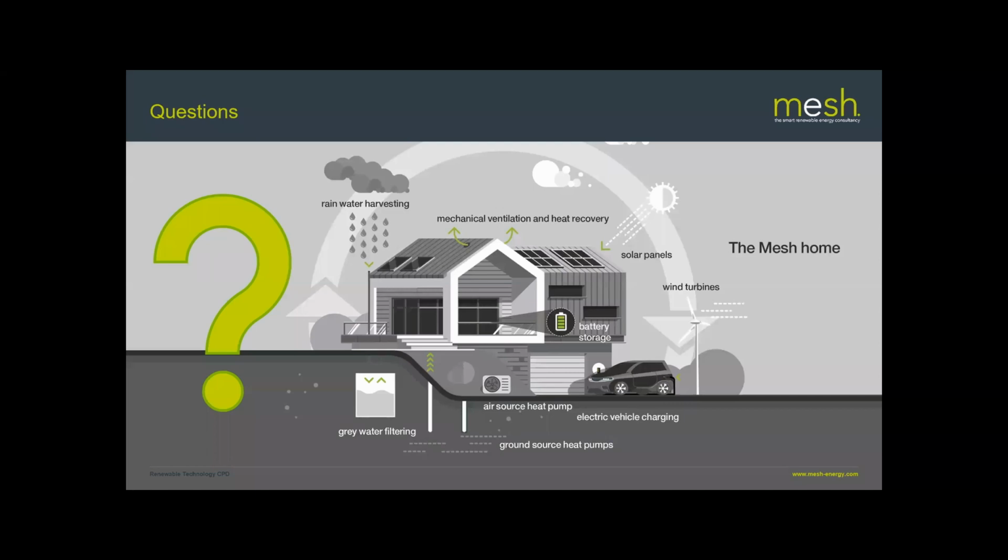So what we do is, as a standard, when we're doing a feasibility study, we get a preliminary ground geotechnical report done by a third party, and get a sort of preliminary borehole sizing done, so we can get an estimate of the ground source of the borehole costs.